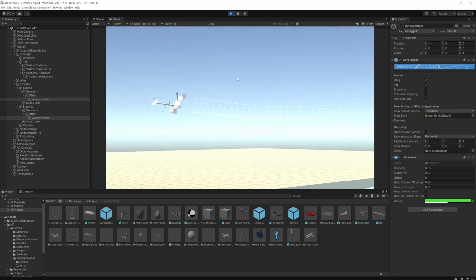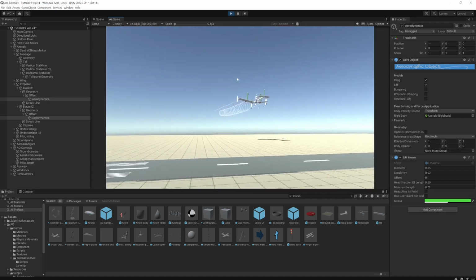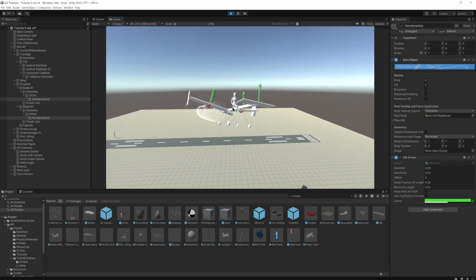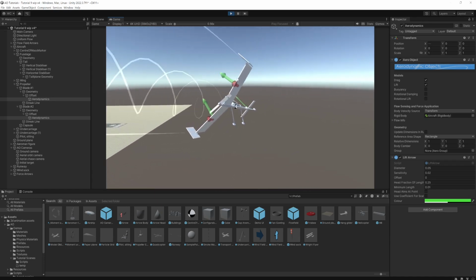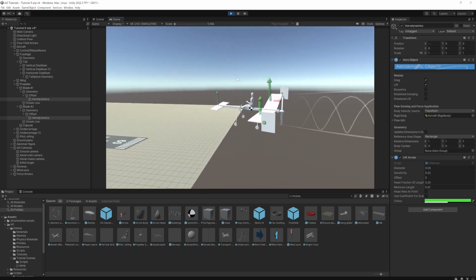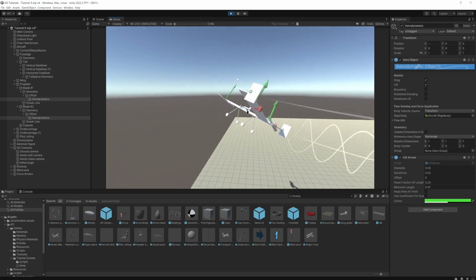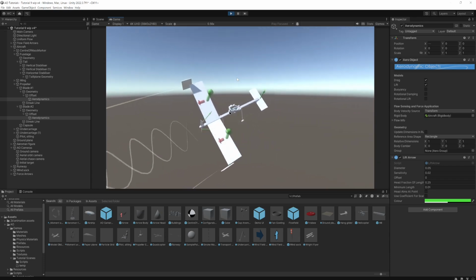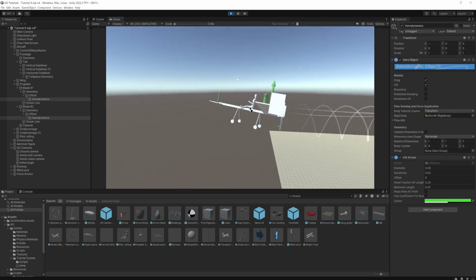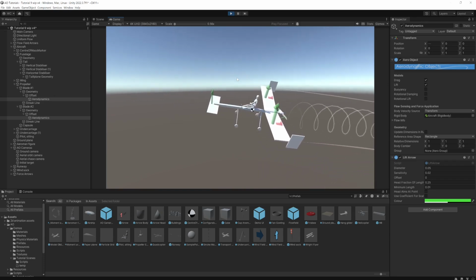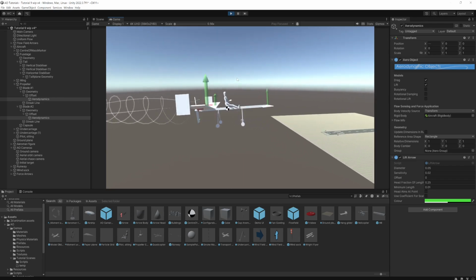And there we have it. We have a canard configuration aircraft made by rearranging a conventional aircraft, and there's nothing in the laws of aerodynamics or Newtonian physics that says a plane like this is any different to one with a tail at the back. It's just a case of getting things balanced and making things stable. So that flies really nicely. We did a little bit of moving stuff around, changed a few gains, but in reality it's fairly simple once you've got an aircraft configuration to use the Aerodynamic Objects to build anything you like, experiment with designing your own aircraft.